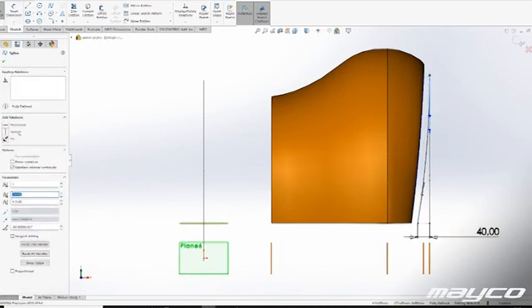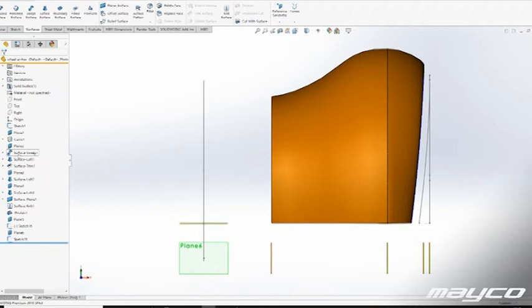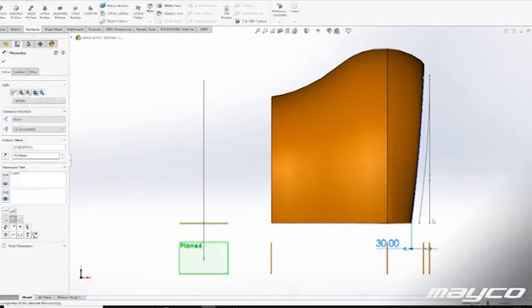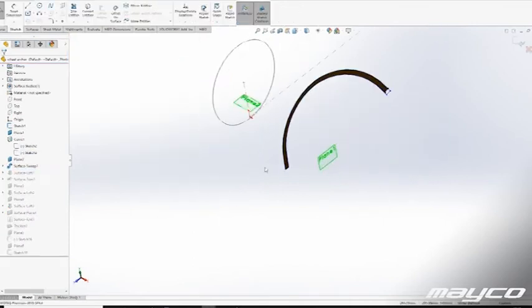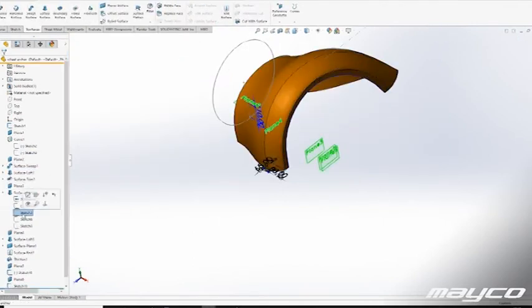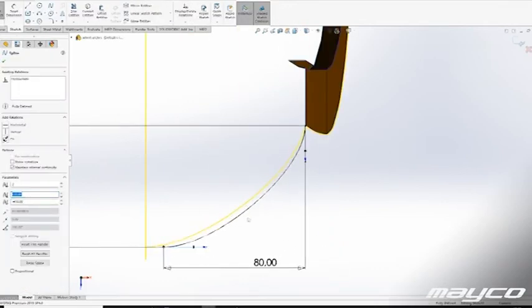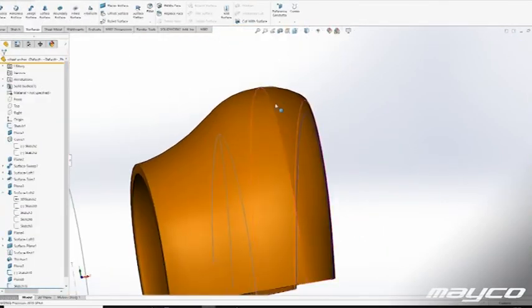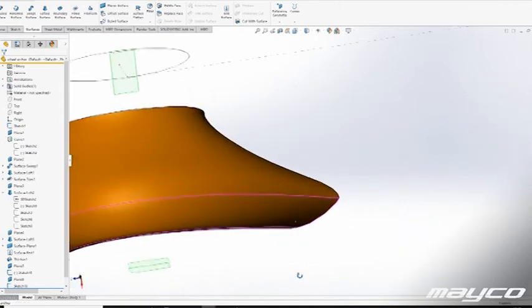So what you either need to do, and you saw me do that at the front with the wheel arch, is that you make a square that extends past what you want and then cut it back and then say that's it. If you do it like that, it's fine. So that's option 1. Option 1 is just make the plane bigger or the surface bigger and then trim it back to whatever shape you need.